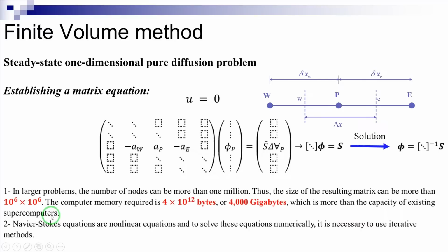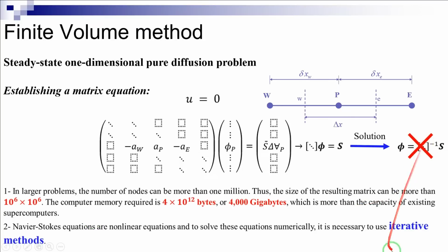2. Navier-Stokes equations that govern fluid dynamics are nonlinear equations, and to solve these equations numerically, it is necessary to use iterative methods. Therefore, instead of using the inverse of the matrix, different iterative methods are used to solve the discretized equations.